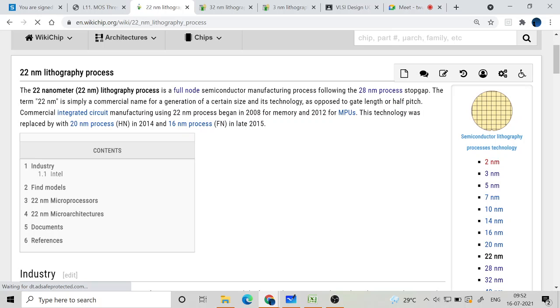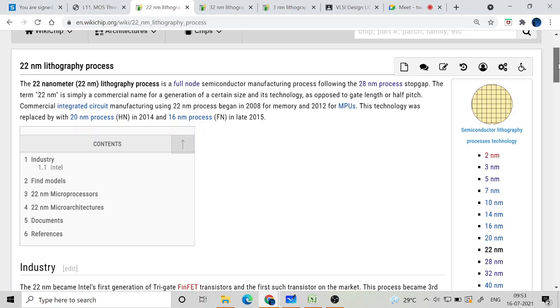the critical step involved in the entire manufacturing, and that takes roughly half of the cost of manufacturing, because that process is repeatedly done. If you look at the manufacturing process, lithography is done like 30 times, 40 times, etc. For every pattern that has to be made in the chip, you have to transfer the pattern from the computer design, the layout design, into the chip. So that is the most critical step.